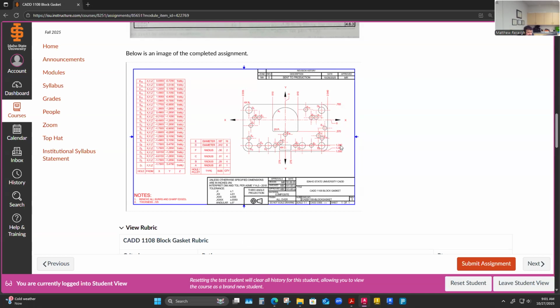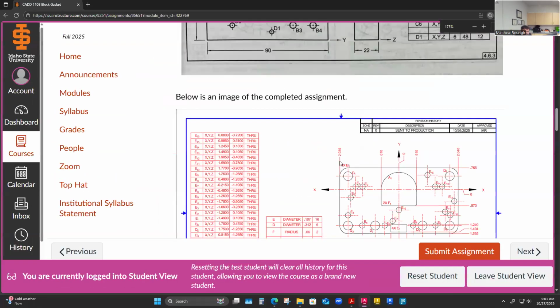And most of them I just keep straight. The reason I start moving the dimension beyond straight is it might conflict with something here. It conflicts with the axis, so I pull it slightly. But I am trying to line up the dimensions. Maybe the decimals are lined up across vertically and horizontally. I'm not just staggering them in some really weird way.